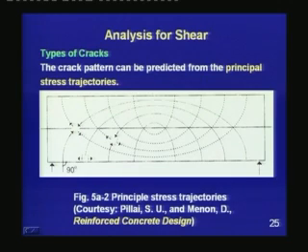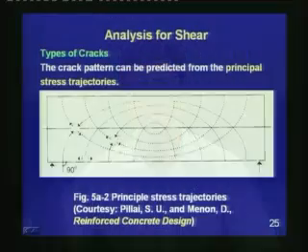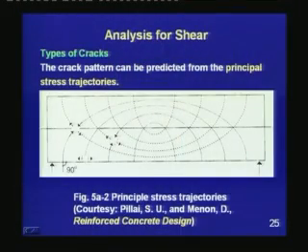The crack pattern can be predicted from the principal stress trajectories. In this figure, the solid lines give the trajectories of the compressive stress, and the dotted lines give the trajectories of the tensile stress. As we know, the cracks form perpendicular to the tensile stress, or they are parallel to the compressive stress. Hence, the formation of the cracks follows the stress trajectories of the compressive stress, and what we find